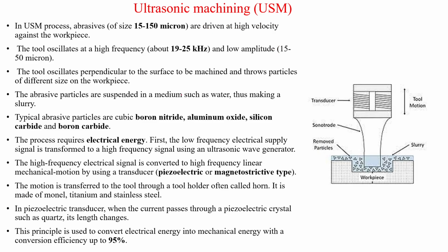So what happens? This transducer is responsible for the reciprocating movement of the tool. This is the tool, you can see there, which is continuously moving up and down. So the tool moves up and down on the workpiece over this slurry. This tool presses the slurry, this thick slurry, onto the workpiece.